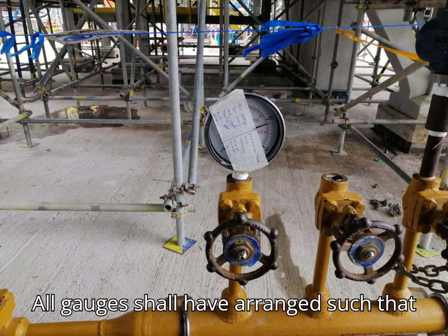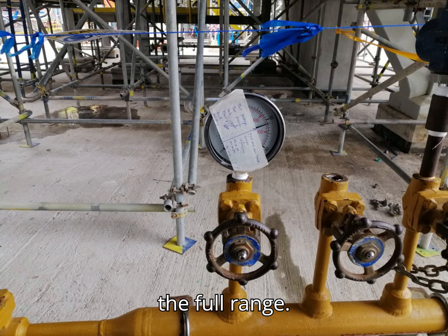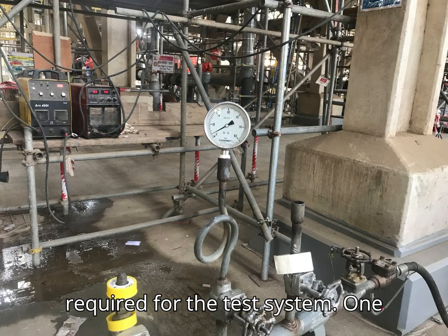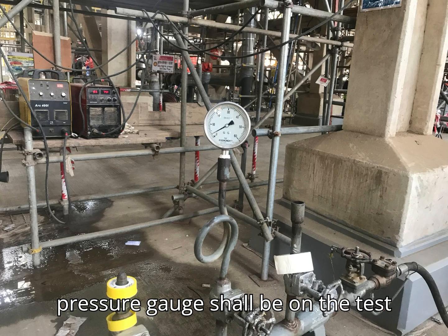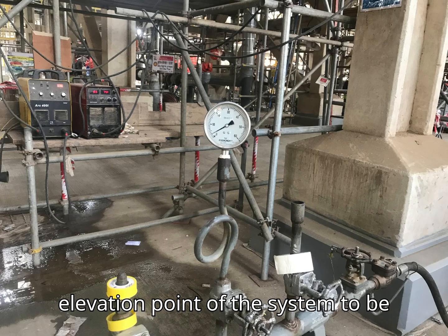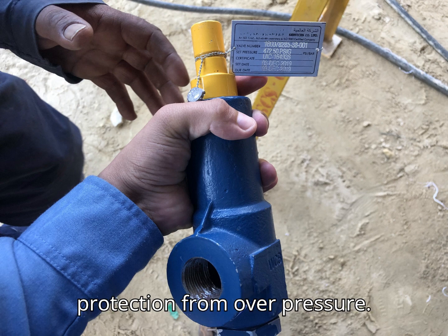All gauges shall have a range such that the test pressure is within 30 to 80% of the full range. A minimum of 2 pressure gauges are required for the test system. One pressure gauge shall be on the test manifold and the other at the highest elevation point of the system to be tested.